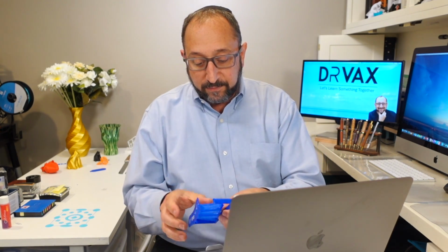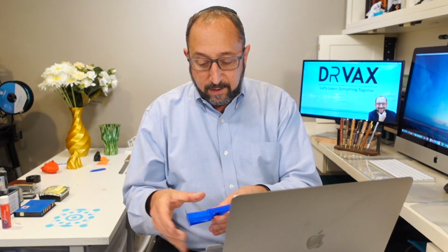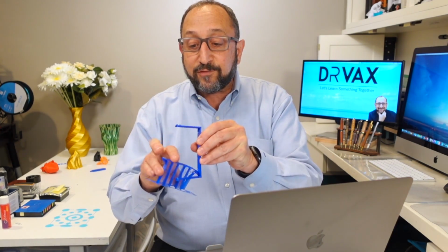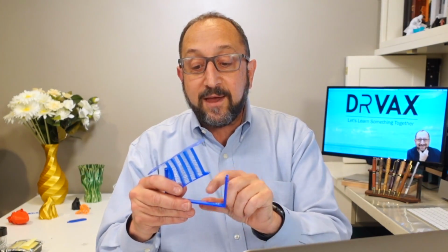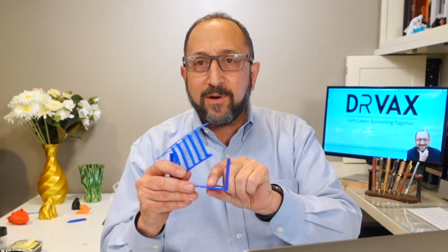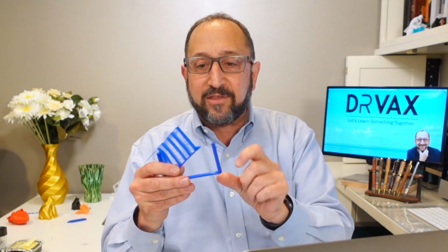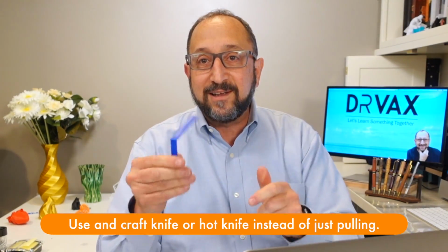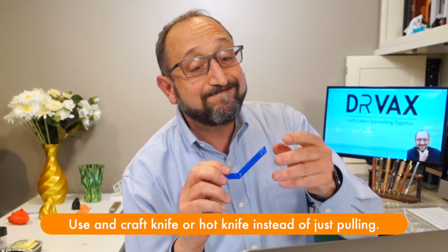And you'll see this is one of the problems with interfaces. It makes it much harder to get the supports off. But you'll see here that there's actually a surface on top of the supports. That's going to make for a very smooth print where you don't end up with problems. But if for some reason this ends up fusing together, then it makes it very hard to get the supports off. I'm going to have to do quite a bit of work to clean this up. And you can see if you try too hard, you'll break your model. So support interfaces can lead to nice smooth surfaces, but sometimes they're quite hard to get off.